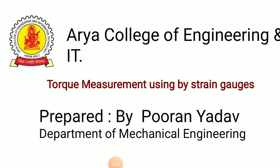Today's topic is torque measurement using a strain gauge. So now we define the strain gauge. A strain gauge is a device used to measure the strain on an object. In simple words, the strain gauge is a sensor whose resistance varies with applied force. It converts force, pressure, tension, weight into a change in electrical resistance which can be measured.